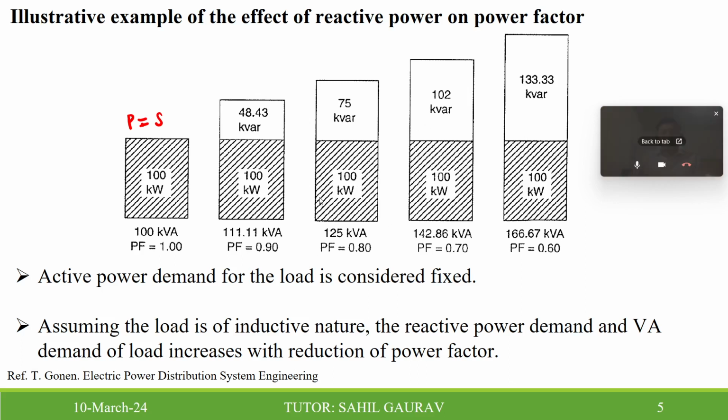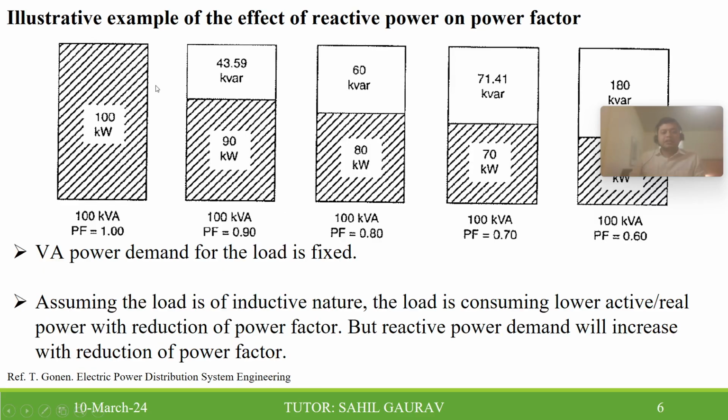In another case, we have assumed the apparent power demand of the load is fixed, and if the power factor worsens, then the load is consuming lower active power with reduction of power factor, and also the reactive power demand will increase with the reduction of power factor.